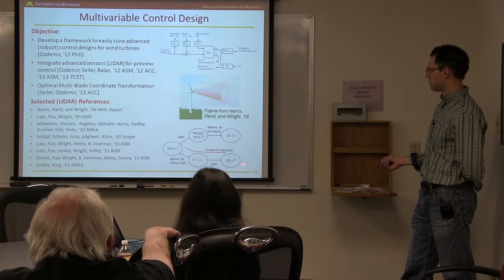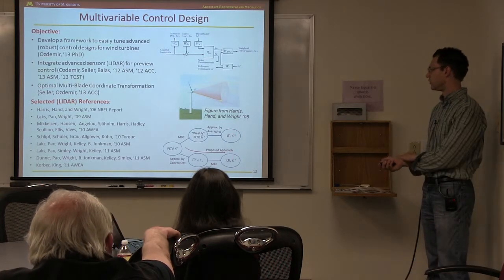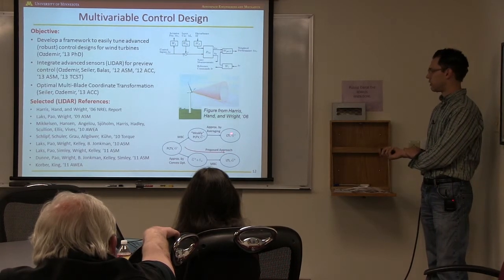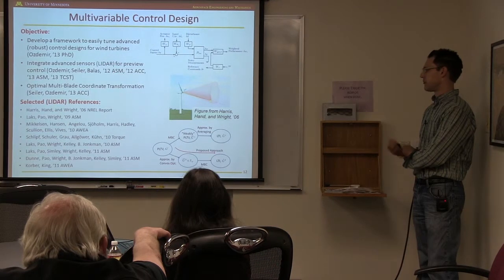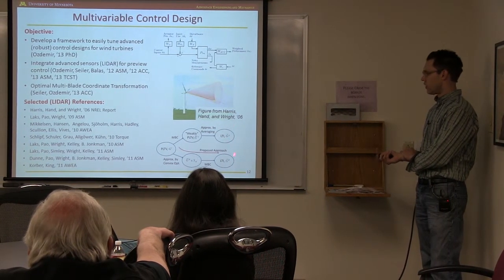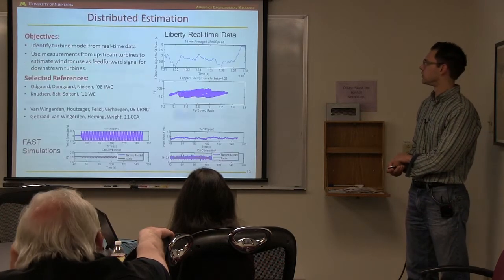And we did this, and it turns out that these two, if you look at the poles or the dynamics, they look the same. But if you look at from input to output, so by that I mean you actually look at the B and C matrices in the state space models, these two approaches give you different dynamics. And from a controls point of view, I'm not sure how this affects the control design, but I think there's some interesting questions about, what is the right LTI approximation here? So I think those are interesting questions.